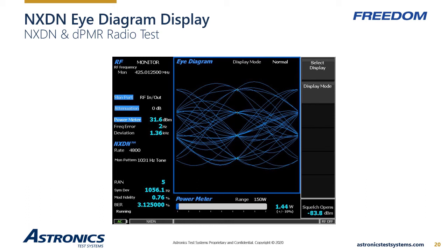Bit error rate is only useful when measuring at the very edges of the radio coverage. And remember that the quality of a digital signal behaves very differently from an analog signal. Analog signal quality fades in a smooth way at the edge of your coverage area. Digital signals are crystal clear much further out, but once the bit errors start, then the quality degrades very sharply for small changes in signal strength. Keep this in mind when looking at weak signals over the air, whether you're using a radio or a repeater.